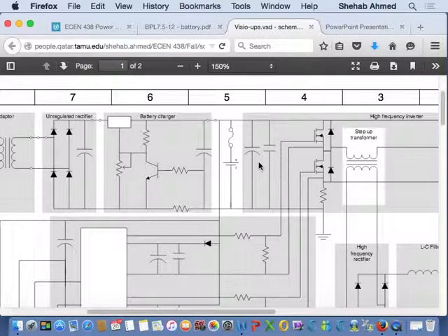So I don't want to just put the battery across the rectifier, the DC input. I would like to put a controlled voltage source in there, so that I can charge the battery at a constant rate. Because the same thing as discharging, charging at a constant rate allows you to understand the lifetime of the battery. It will allow you to say, okay, this is my design. This is what I'm doing from a design perspective. I'm not just throwing things out in the air.